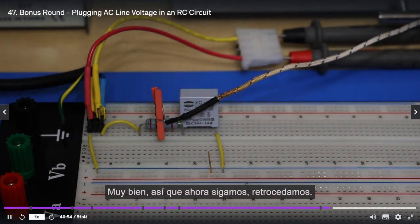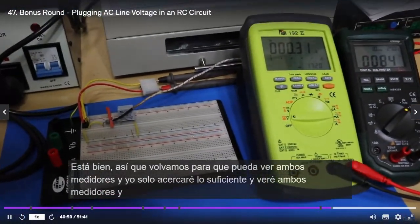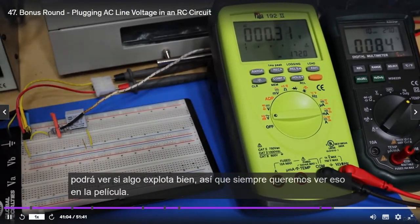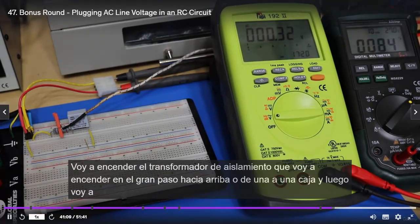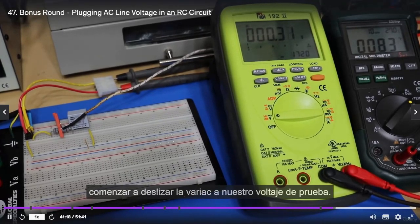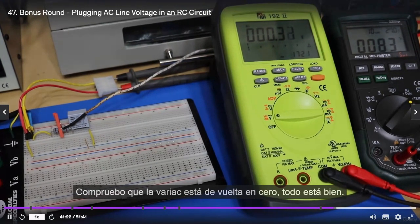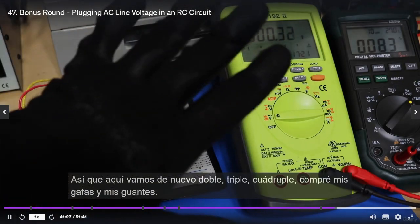Now let's back away, so you can see both meters. I'll zoom in just enough so you can see both meters and you can see if anything explodes, right? We always want to catch that on film. I'm going to turn on the isolation transformer, then turn on the big step up or one-to-one box, and then start sliding up the Variac to our test voltage. I check the Variac, it's back at 0, everything's good, so here we go. Again, double, triple, quadruple check. I got my goggles, I got my gloves on.